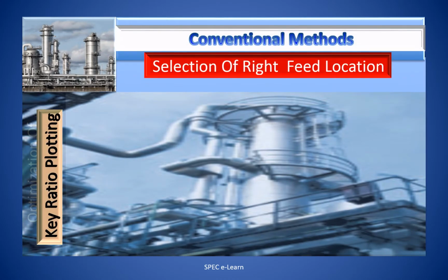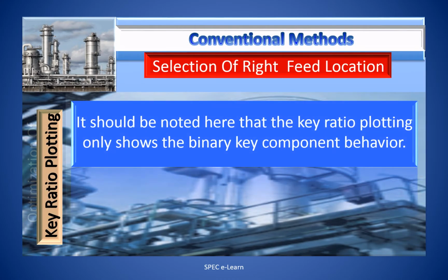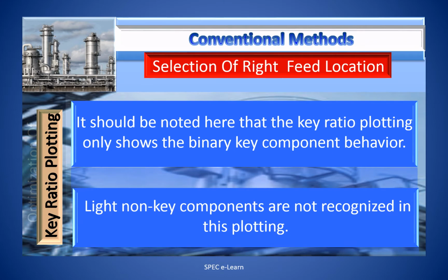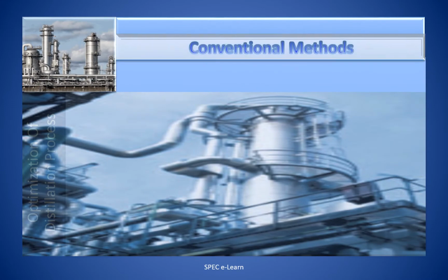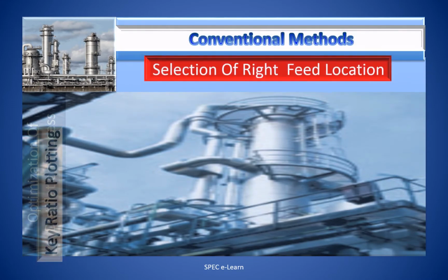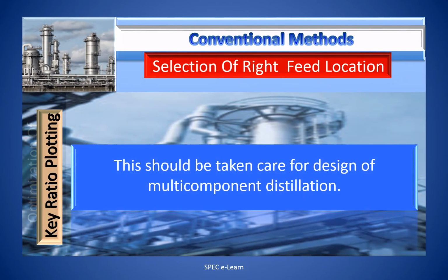It should be noted here that the key ratio plotting only shows the binary key component behavior. Light non-key components are not recognized in this plotting. This should be taken care of for design of multi-component distillation.